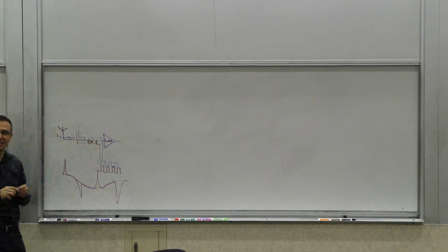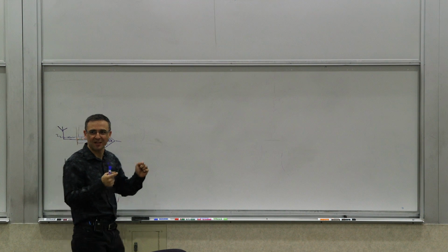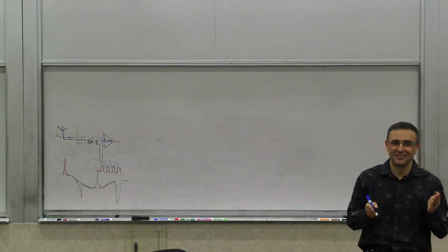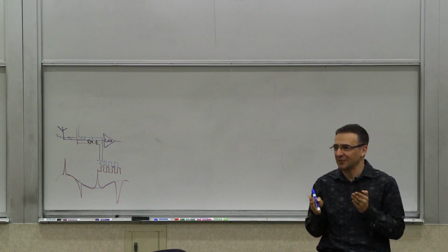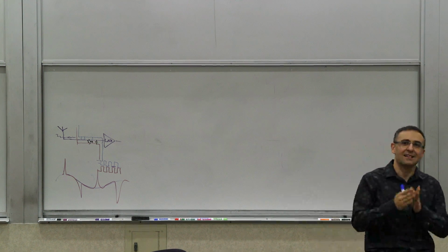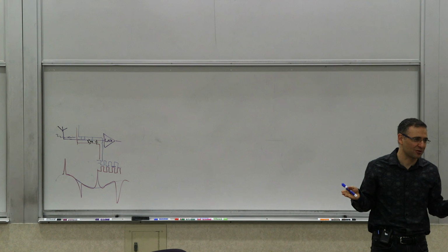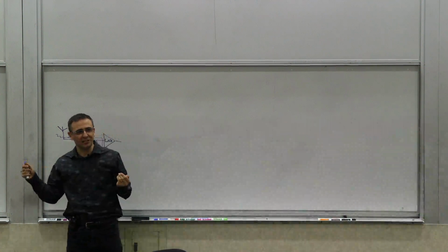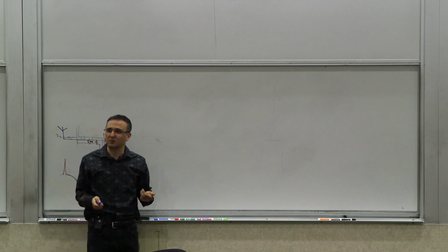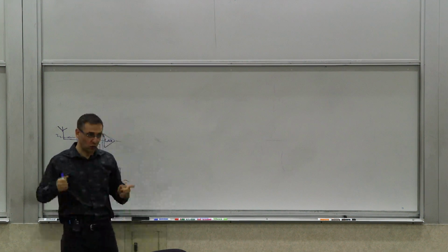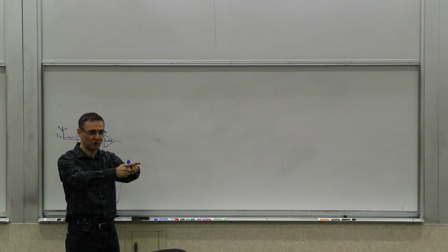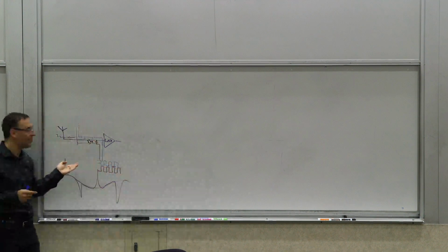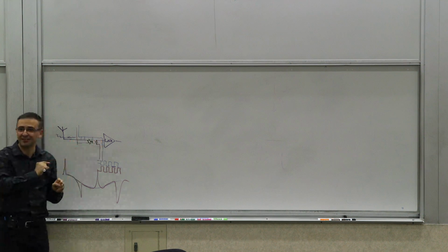So you have two of these that are coupling the opposite amounts in the opposite direction into the signal, and you have to make sure that these are well balanced, right? This coupling. Yeah, this could work. This could help to some extent. But you can start seeing that it's a little bit challenging to do in a systematic way. First of all, anytime you're routing a clock, you're routing two lines instead of one. So your routing becomes more complicated. You have to drive two lines. And then you have to make sure that it remains symmetrical.